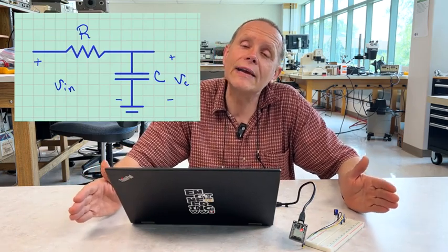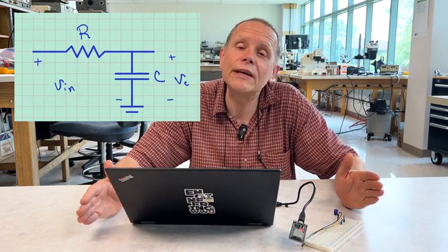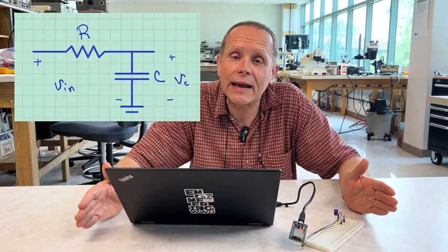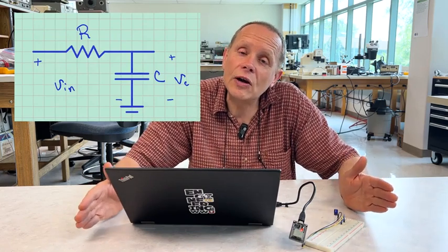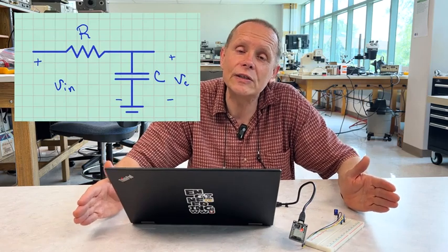And so the eigenvalue, or the pole, or the root of the characteristic equation that you learned about when you were learning about linear systems before, is going to be changed using a thing called state feedback. We're going to change it from e to the minus t over RC kind of solution to e to the minus 10t over RC. So it's going to go 10 times as fast.